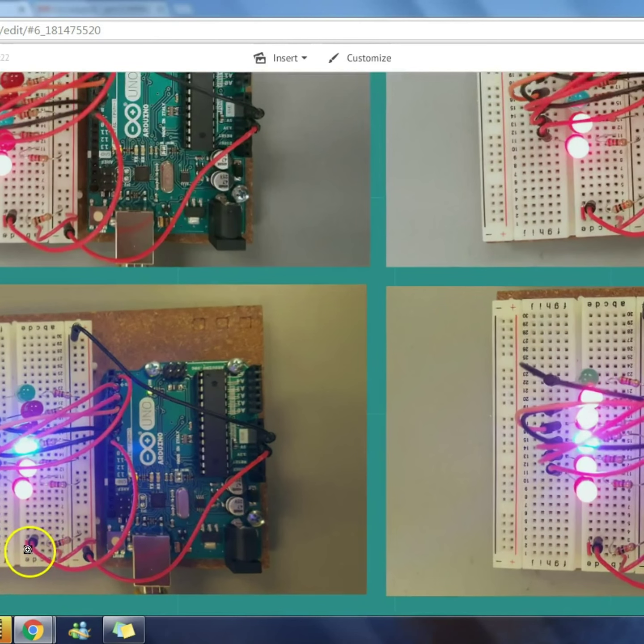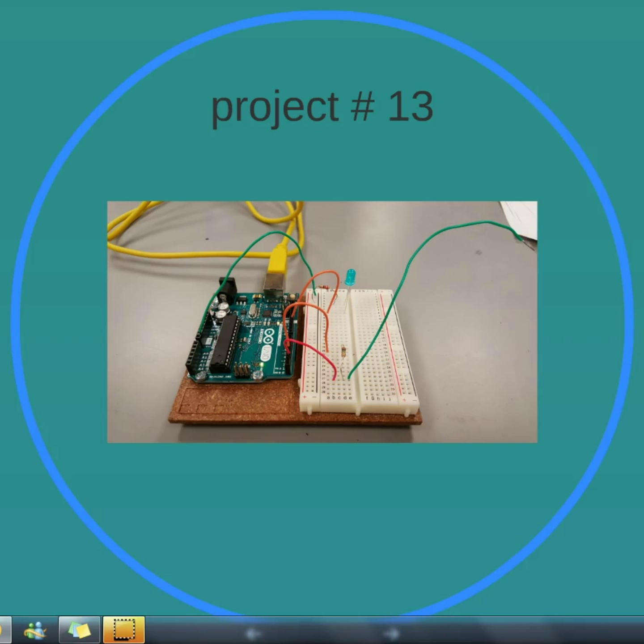Our second Arduino project was number 13. It is called Touchy Feely. The objective is to turn an LED bulb on when we touch a piece of conductor on the circuit. The Arduino constantly measures the capacitance of the circuit. When the conductor is touched, the capacitance is increased due to adding your body's capacitance. The Arduino senses this change, thus lighting the bulb.